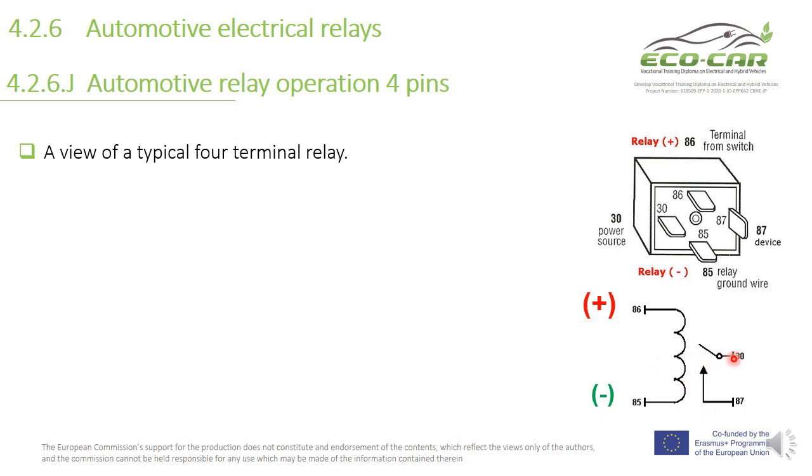And we can measure the resistance between pin or terminal 30 and 86. It will be zero, nearly zero. And if we disconnect the power source on this side, the resistance between 30 and 87 is very, very high, infinity, for example.